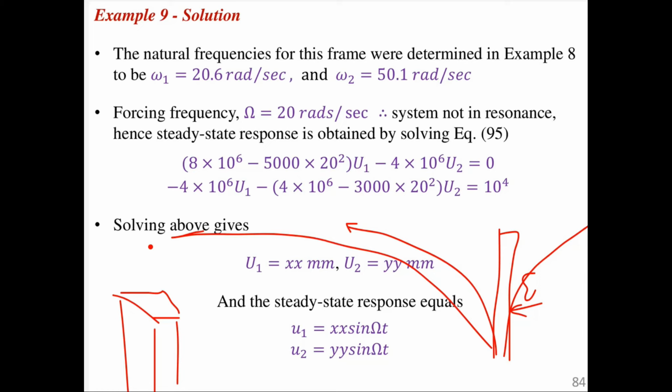Although the structure may not collapse, although that timber member or that steel beam will not collapse, if it deflects such that it affects the opening and closing of the door, that's serviceability. Or if there are unsightly cracks occurring, then you can say the failure has occurred, not the ultimate failure, but when you do a check against the serviceability limit state, it has failed. Okay, so it depends on what kind of design you are talking about when you talk about failure.